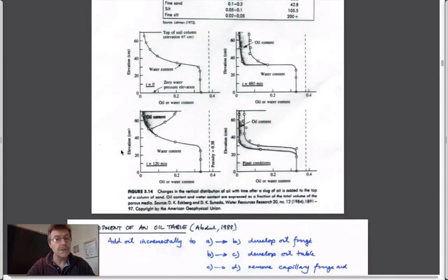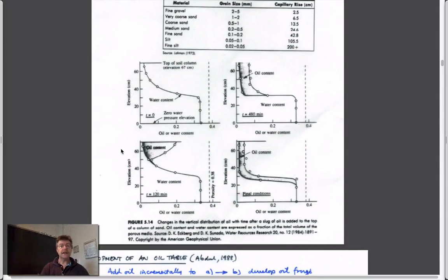But remember we looked at this example last time. It kind of looks like the saturation profile as you go down at depth. Choose a particular height here. This is the surface. This is a small saturation of the NAPL. This is deeper. This is about the same saturation of the NAPL. If you look here, then the saturation of the NAPL is basically between this point and this point, so relatively a big number, which sits on top of the water table.